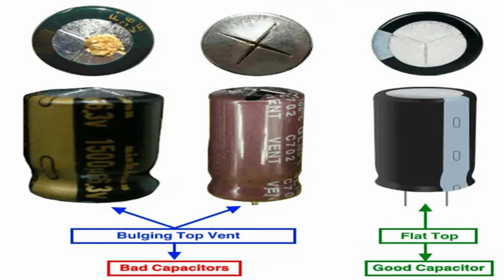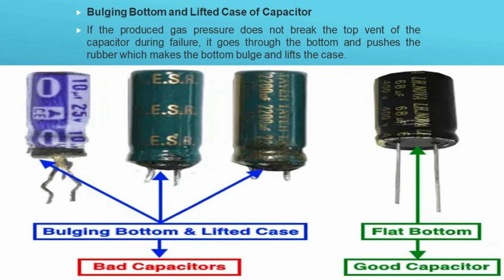The discharge time can also be calculated. In this case, the time taken by the capacitor to discharge to 36.8% of the peak voltage can be measured. Good to know, the time taken by a capacitor to discharge to about 36.8% of the peak value of the applied voltage can also be measured. The discharge time can be used in the same way in the formula to find the value of the capacitor.